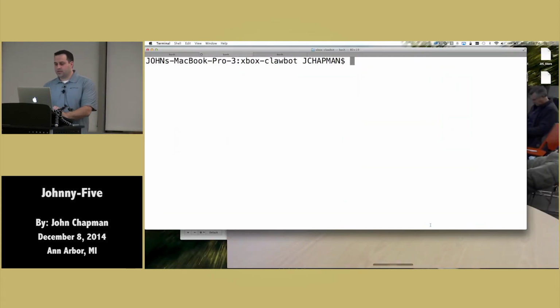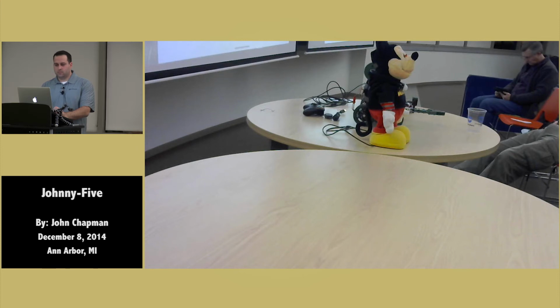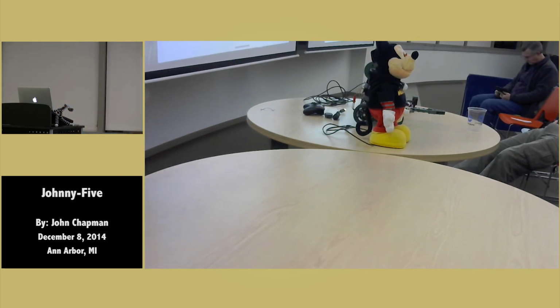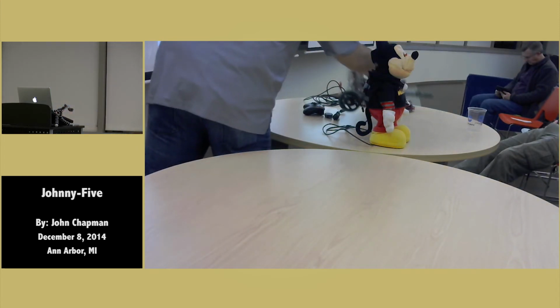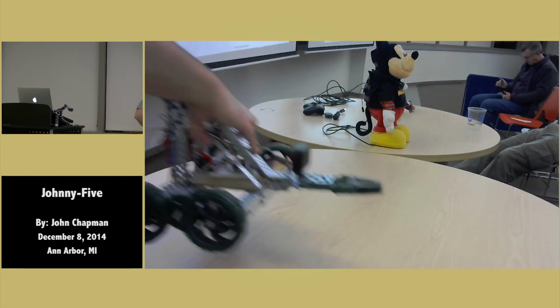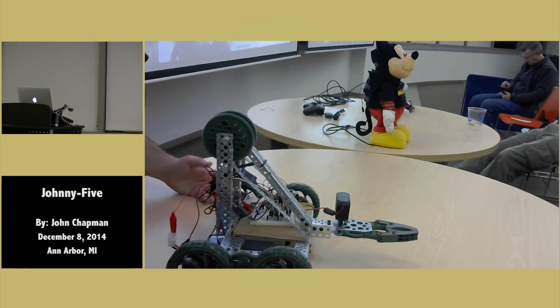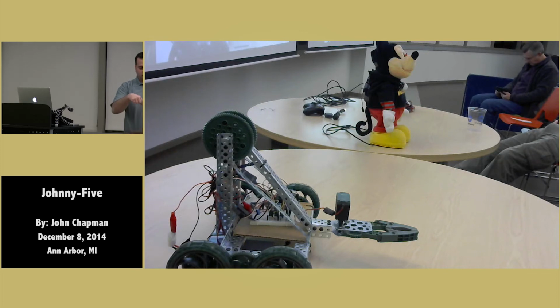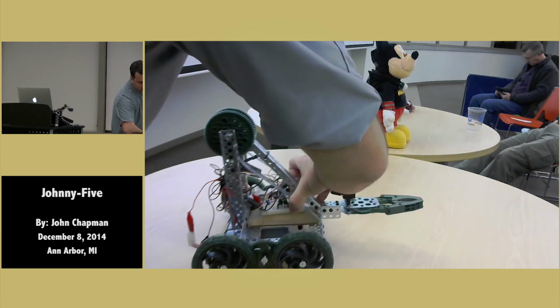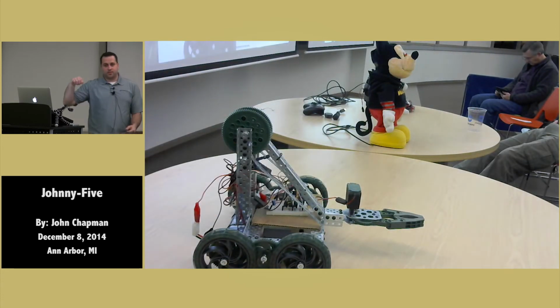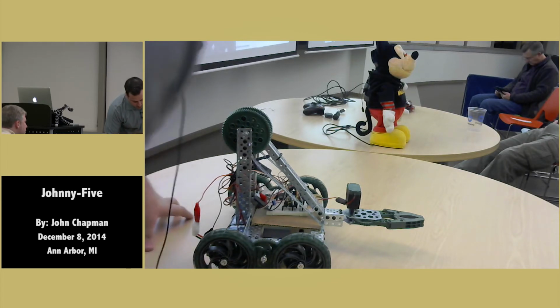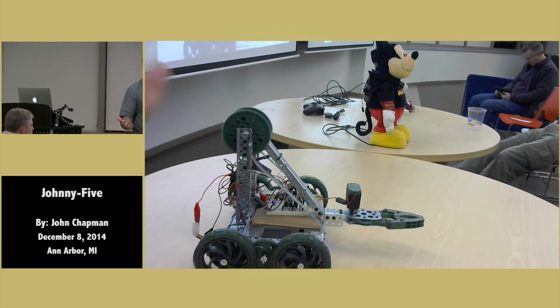All right, so let's get this thing going. And one thing I'm also very careful about now is, if you looked really closely, you see that there's some burn marks on this robot. This is one of the ones that caught fire. Basically what happened is in transport, I have a little breadboard here and one of the wires came loose. I connected the power, it shorted the wire, sparks flew. So be very careful, right? So I always check every time I turn it on, make sure everything's plugged in correctly after that experience.